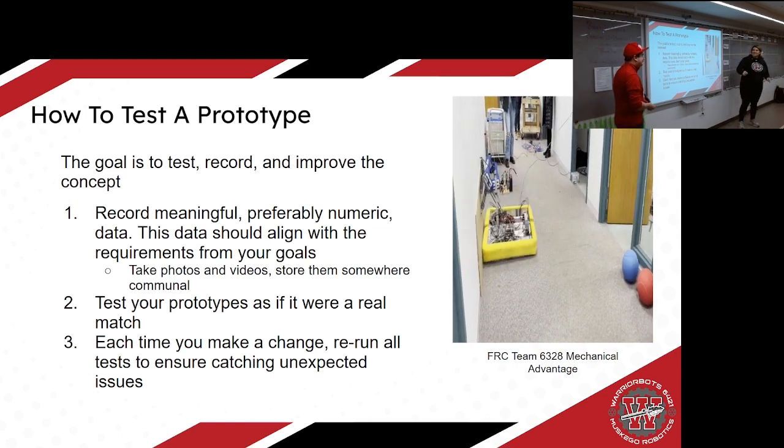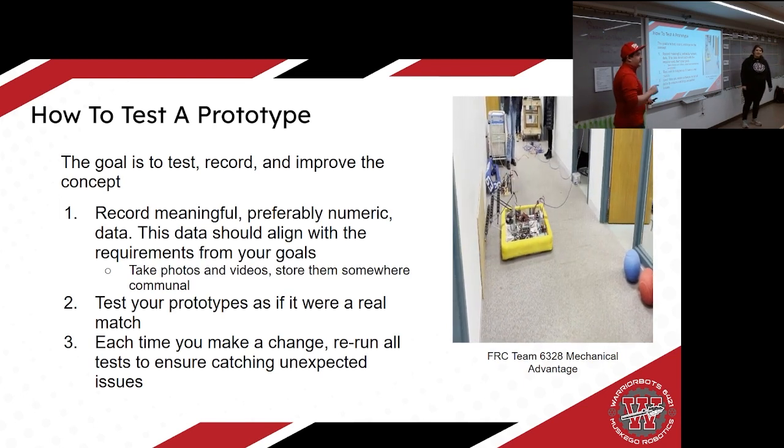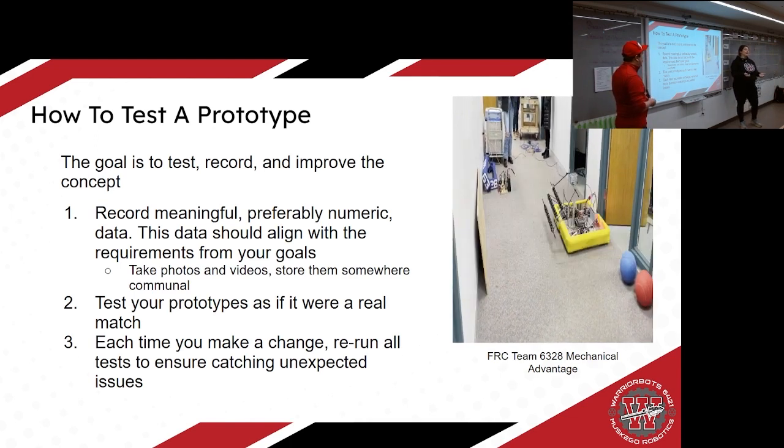Testing realistically is extremely, extremely important, and that means your driver is going to crash into stuff, or other people, or things will crash into you. I don't care if you say they won't, they will. Drive your intake into a wall, because your driver is going to drive your intake into a wall at some point. I don't care how good they are. It's going to happen. Make sure that you are driving into what you are trying to pick up. Or if you're on a furniture dolly, those work really well if you have swerve or old drive bases.